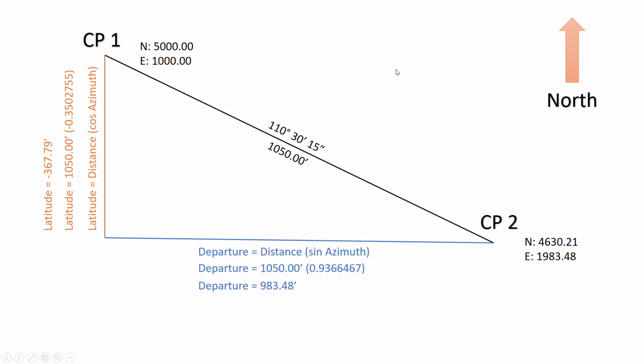We're going to be given a stakeout point, so say if we had 4 points, the locations of a building, we would know the coordinates of those buildings. If we know the coordinates, we can work backwards, compute a component and a component, and if we have the departure and latitude components, we can then compute an angle and a distance, and that's radial stakeout.